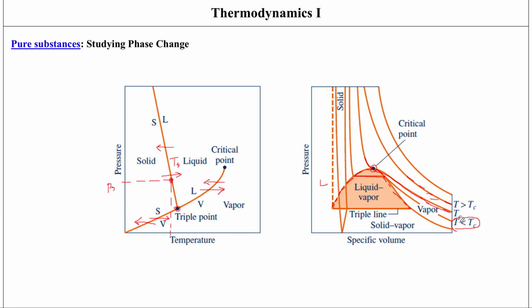So what this means is that if I had, let's say, a temperature that is less than the critical temperature for my substance, and I had a certain specific volume, and now if I reach this point, I will not be able to basically increase the pressure for my substance until I get to this point here. What I mean is that this can't happen, that I reach here, now I'm in the middle here somewhere, and now the pressure starts increasing from here.